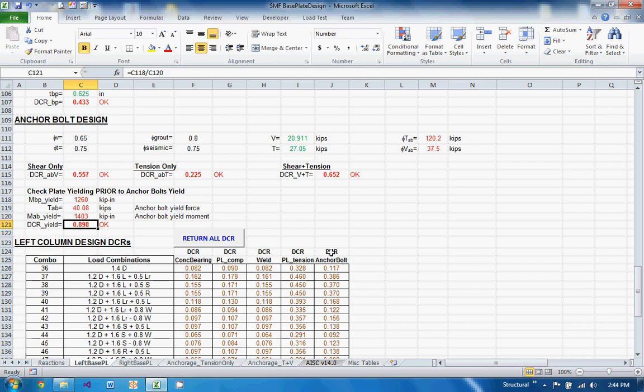If they ask us, let them submit it to us and we'll review it, because typically our holes are oversized already. So if they're going beyond that... in that case, if they want to weld a washer plate to take care of it, if that's faster. I don't know. At this time, what would I worry about? Did they use their anchorage or not? I think they did, so it should be okay. The holes are already oversized for 1/16. They cannot go over that dimension by another 1/32.